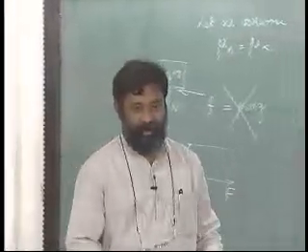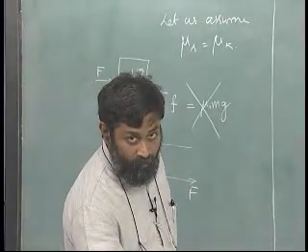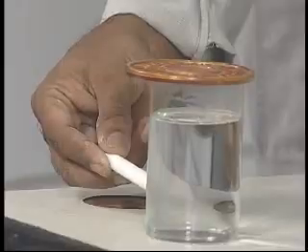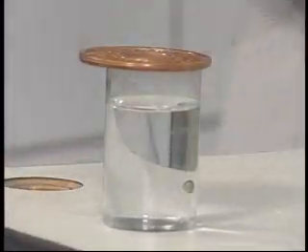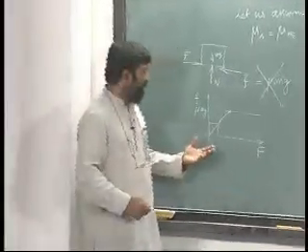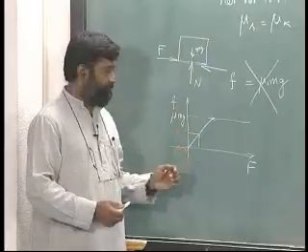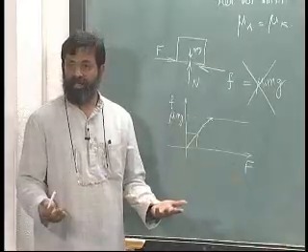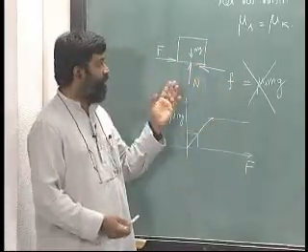So when I have this body and I am applying a force, for it to start to move I need to apply a force equal to mu times mg. When it starts to move, mu kinetic, the coefficient of kinetic friction, will play a role. Okay, this is often a mistake that students make, and please remember small f is equal to capital F comes purely by equilibrium. If I look at this free body and find out,